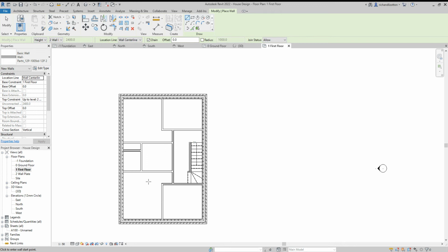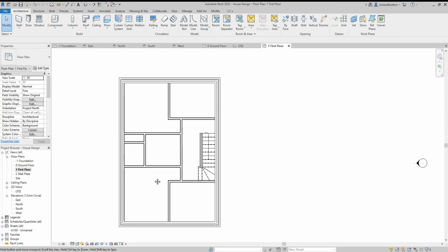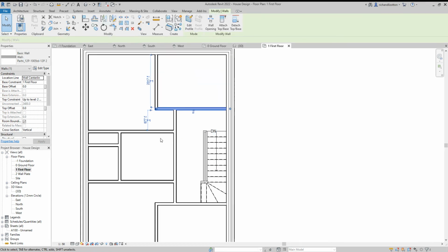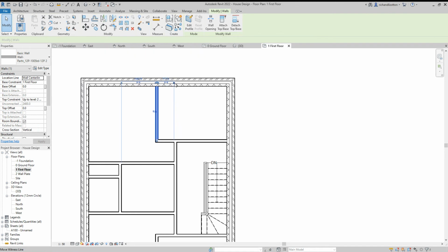Okay, let's have a little look what we've got here then. So now I'm going to actually start positioning them more accurately. Now you'll notice it brings up the dimensions, and if you grab the blue dot at the end of one of the lines of the dimensions, you can line it up with something else. So I can see there I've got 900 from the stairs to the wall, 927. I'm going to put the door over by here, so I might actually make that 900. Press enter. Then I'm going to click on this wall, and let's see how big each of these bedrooms are.